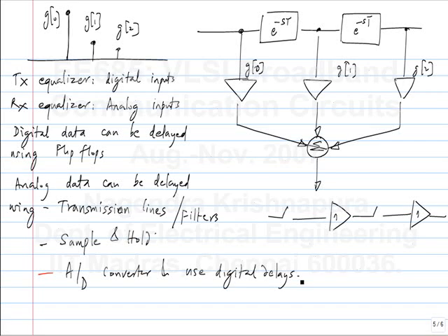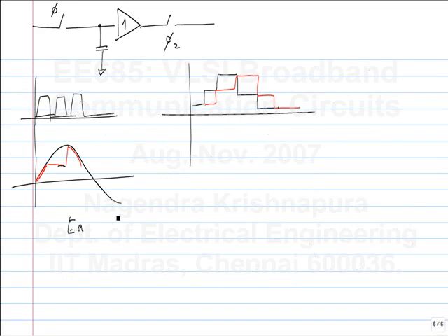So from all this, from the implementation point of view, is it easier to have the equalizer in the receiver or the transmitter? Transmitter. Because you can use flip-flops to delay the data, and then you can sum them. As far as adaptation is concerned, that's a different issue. It's harder to adapt an equalizer when it's at the transmitter. But just to implement the equalizer, let's say now we are talking about a fixed channel, then it's easier to implement it in the transmitter. What to do about adaptation, we can see afterwards.